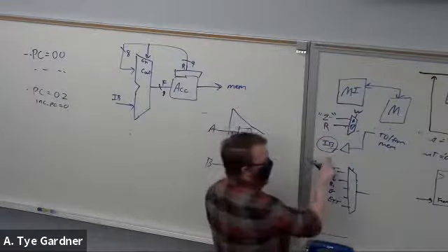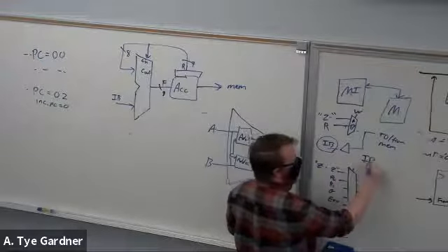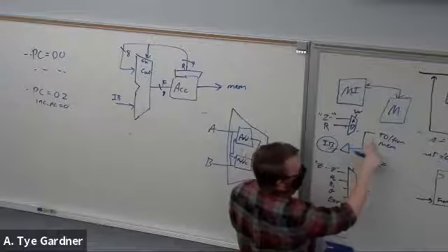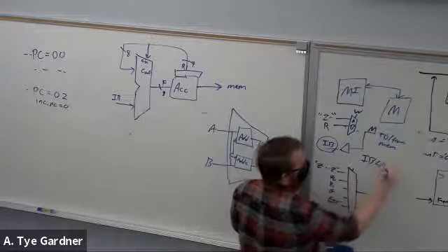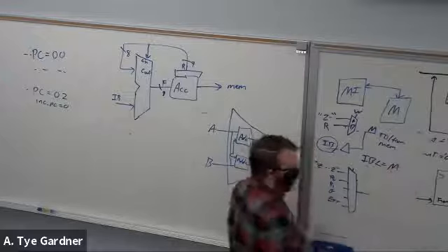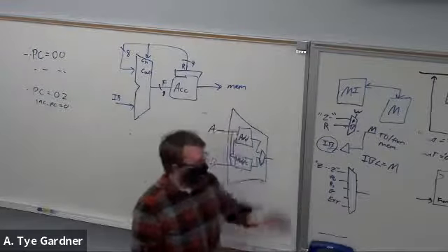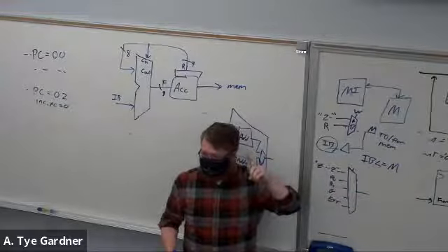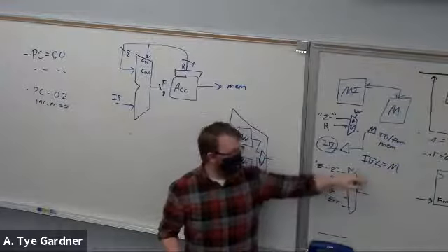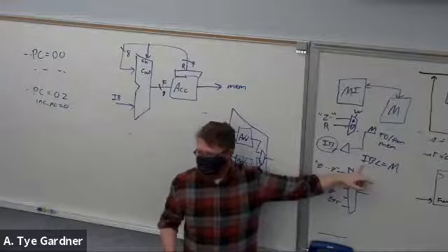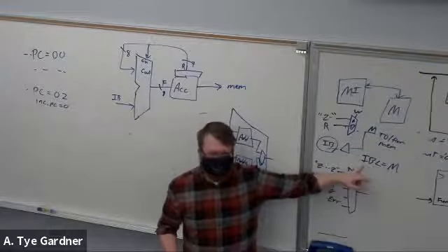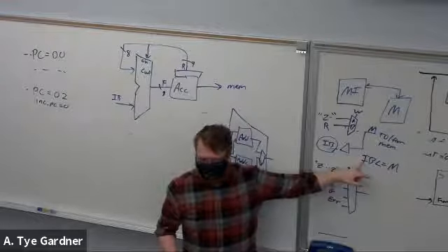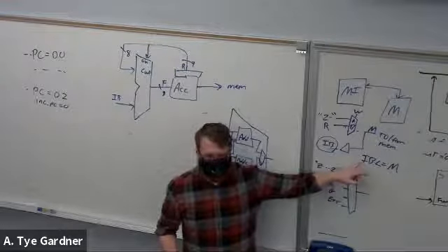And a buffer, like in this case, is just saying, what do I call this? I'll just call that signal M for now, right? That's a buffer. It's a D flip-flop if it's in a process, so be careful. If it's combinational logic, that's a buffer. That's one of the things you have to be careful about. Inside of a process, this is a D flip-flop. Outside of a process, it's a buffer.